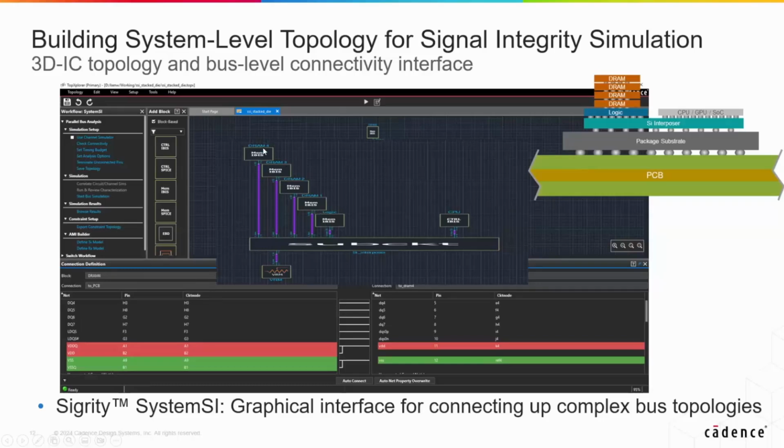In this case, we're using memory IBIS models to connect to that interconnect model, and then look at the receiver, the destination, the voltage, the memory controller, to be able to read and write and look at the data flow in both directions, read and write, for a multi-fabric board package. This is showing the idea here of a stacked memory going through a silicon interposer to the memory controller.